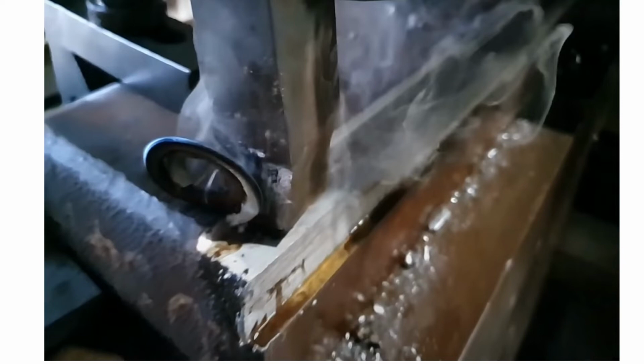As you can see, with the shaper, it's easy to visualize the cutting speed in meters per minute. As with a bandsaw, the cutting feed is directly input or set in the machine from the data sheet. With a rotating tool, a formula will need to be used to convert that value, that is cutting speed in meters per minute, into a speed that we rotate the tool, which is RPM, and the feed rate in which we introduce the tool into the material. We will be looking at those formulas later on in this lecture.